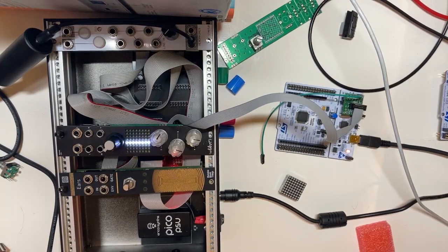ADC. Right. So if we look at the schematic again, it's pretty simple. There are 3 pots connected across ground and 3 volts, and they just go straight to pot 1, 2, 3, which are up here. And conveniently, ADC1 gets really nicely numbered pins, A0 through A15, which are all analog. So I've got the 4 CV inputs, 2 of which are aliased against the codec, and then the 3 pots. So we've got 7 channels of ADC. So now let's just do 7 channels of ADC.